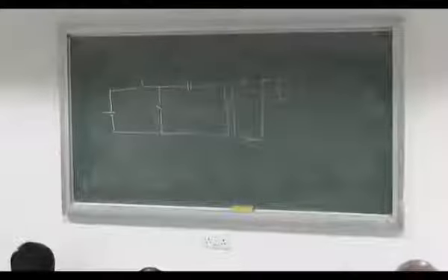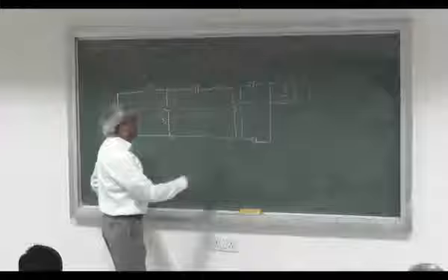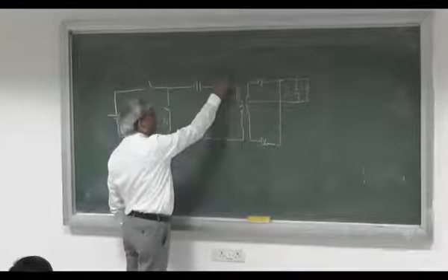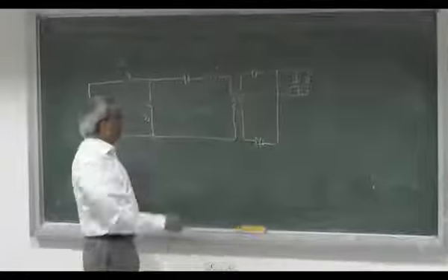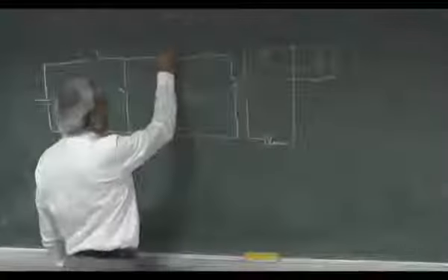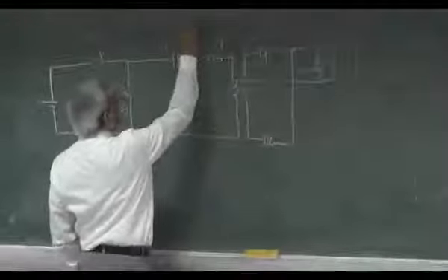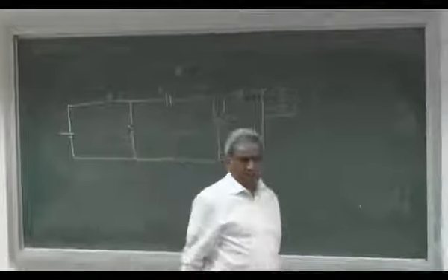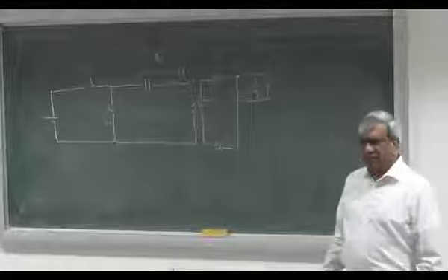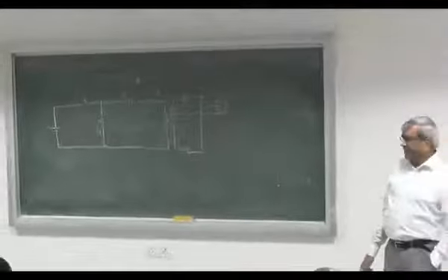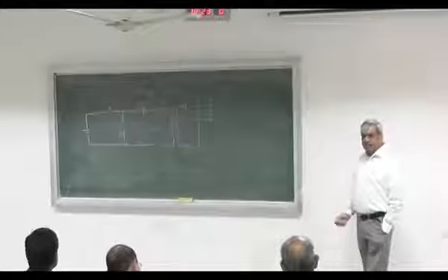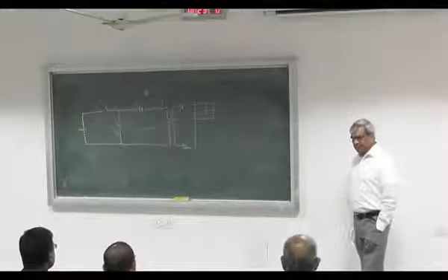One of the things here is that in order to maintain the zero voltage switching, the value of this Q has to be reasonably high. Reasonably high means maybe rather than 1, it is 2.